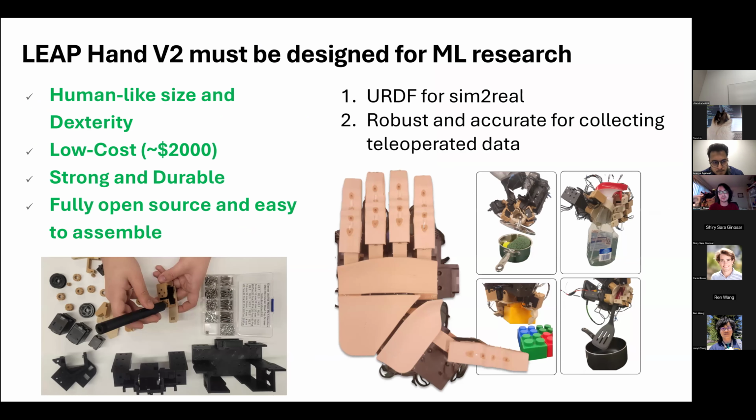We also saw some autonomous results doing behavior cloning. So these are our 2 LEAP Hands on our arms, and we train this with diffusion policy. The nice thing about this is that because the fingers are soft, we see the plate and the 2 arms interacting with the object. Even with them twisting at slightly different rates, the soft hand and the fingers are able to comply around the object.